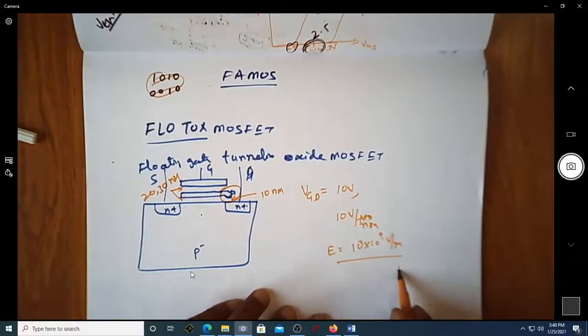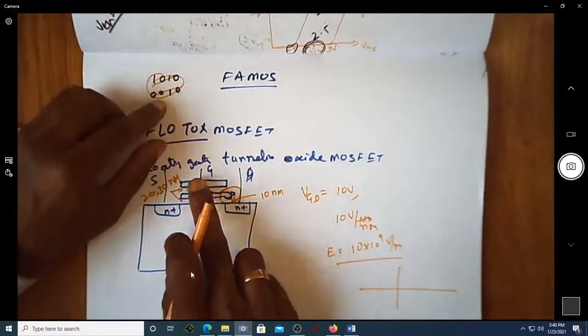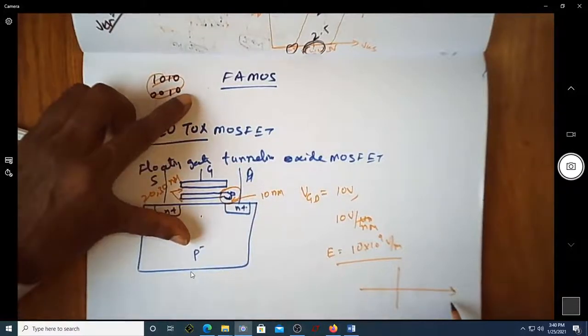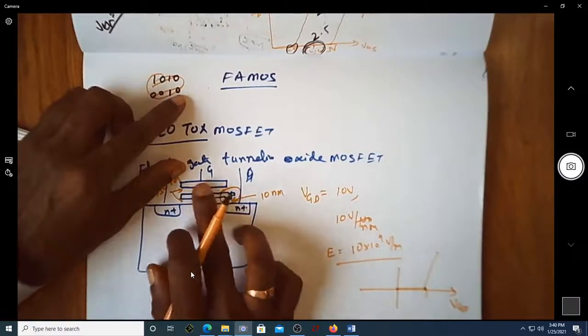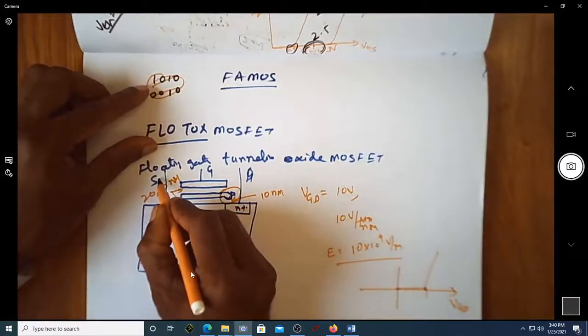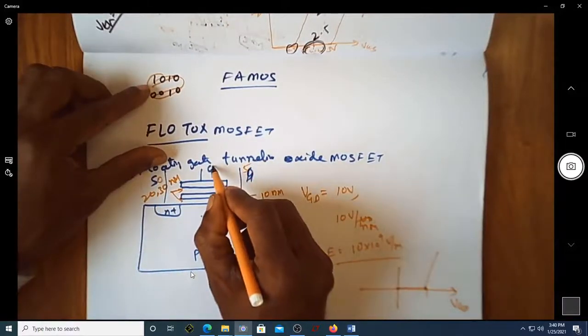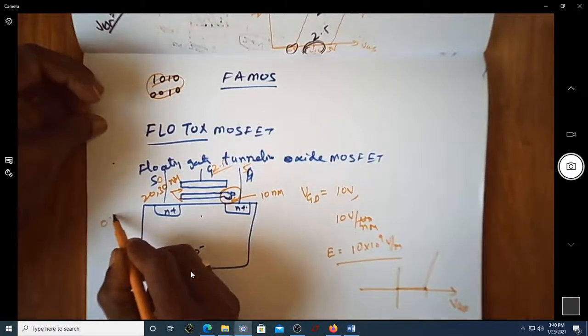That is to say, consider the IV characteristics of this particular MOSFET with respect to only the drain and the gate. Suppose you call this VGD. If the applied VGD is very large, it happens that I can make it turn on at a larger voltage. Under normal conditions, if you are not applying too much voltage to the gate and drain, assume this is 0 volt and this is 5 volt, and if you have 2.5 volt, then under normal operation the threshold voltage is around 0.5.